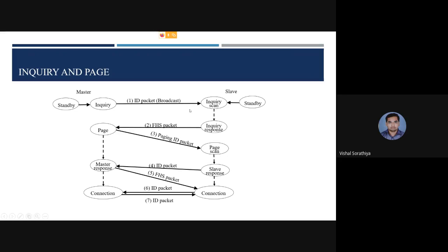Once that packet is shared, like I want to communicate with you with this frequency hopping packet, he will give me the idea that okay, I'm ready, and this is my ID. After sharing the initial information about the sequence in which we are going to send messages, the actual connection is exchanged and all the messages are transferred. So initially in the setup phase, it first exchanges in which frequency hopping manner we are going to share the information. After confirming from both sides, it will start connecting.